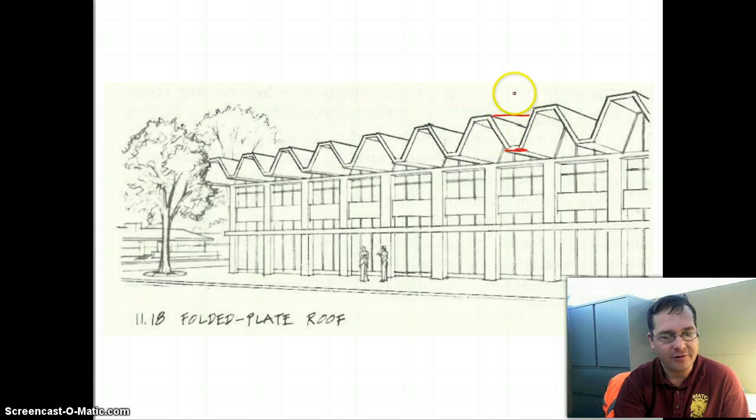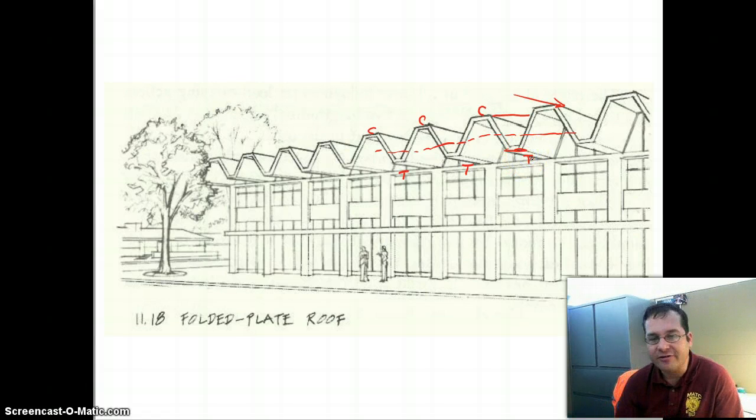So you have to imagine that this is spanning some direction off screen like that, and it's going to take on a sag, which means that these top extreme fibers are in compression and the bottom extreme fibers are in tension. The neutral axis is going to run right through mid-height. So this material, at mid-height, is not carrying a lot of weight, but if you look at the design, the designers have put most of the material in the top and in the bottom of the structure. Again, it's just one of those things that arises out of understanding that as goes the strain, so goes the stress. You try to put the material where it's going to be deflected the most so that it can carry the most of the load.